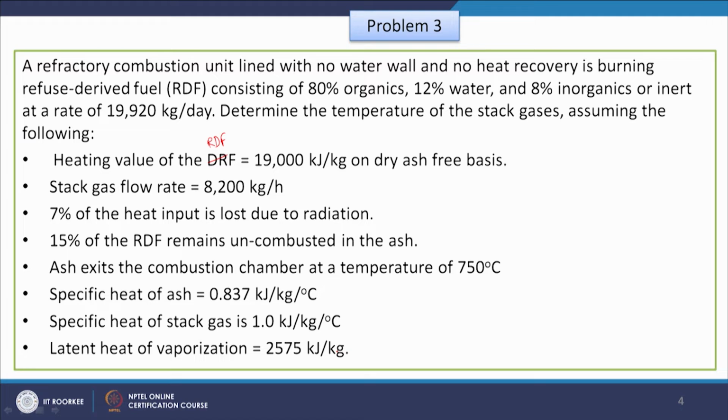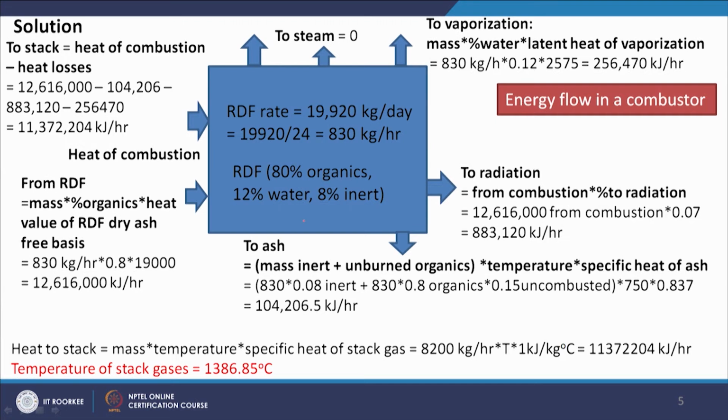Okay. Now, this is a problem related to incineration of the waste materials. So, here this is a combustion chamber and furnace, but in this furnace the boiler part is not included, that means it is a refractory furnace. So, water tubes are not installed in the wall of this furnace. So, there is no steam formation basically. So, the heat which is generated will be going through the flue gas. So, no steam will be generated in this furnace.